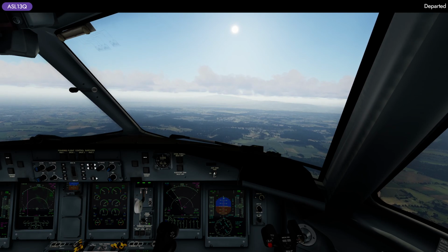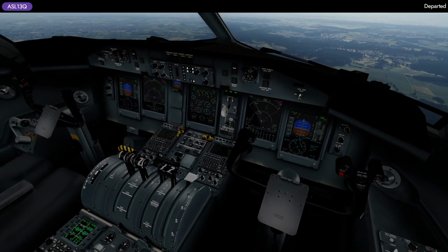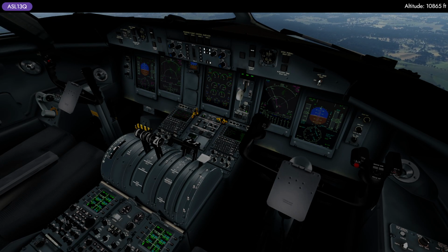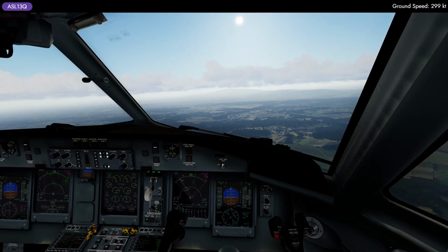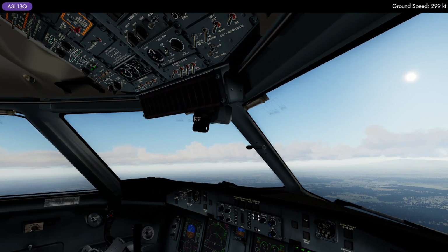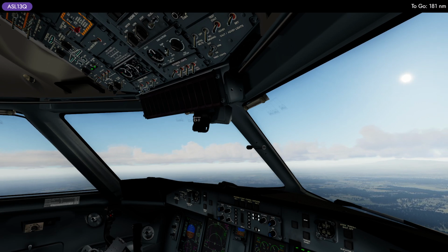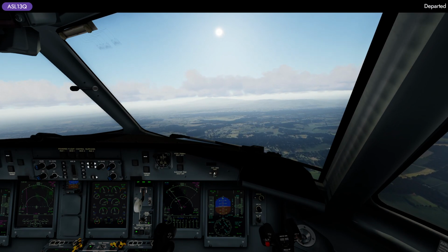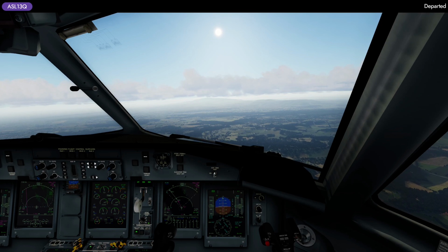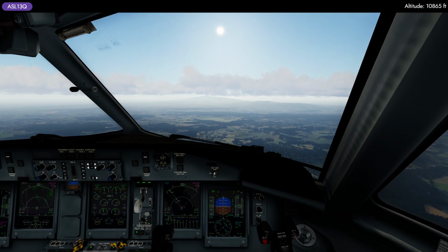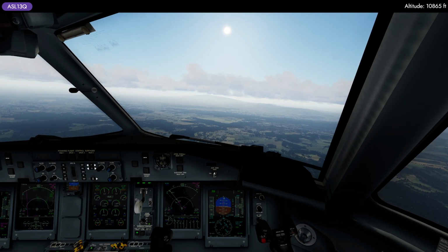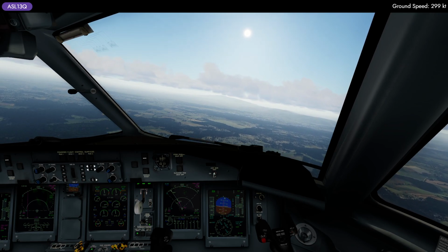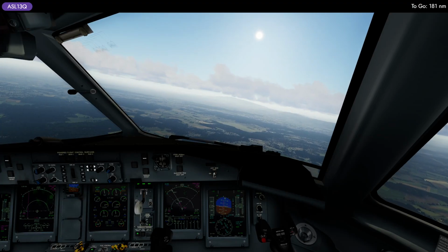Keep an eye on the speed. And basically back to full. Auxiliary pumps on, auto feather on, standby pressure on. And we can turn on again the lights. There we have the localizer. Very nicely, very gentle left turn. Yep, gears remain down.